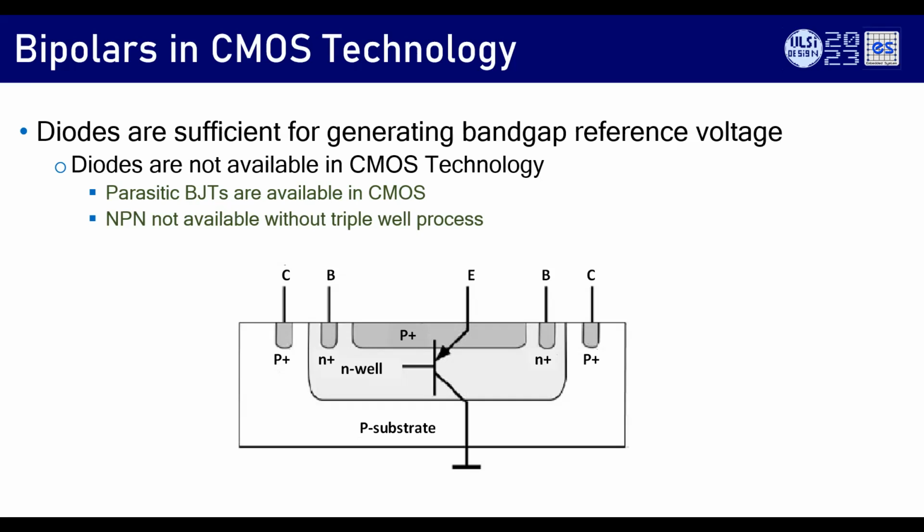So just an N plus inside P sub. Okay, you have N plus, you have P sub. You'll have some other transistors there, right? Yeah. Then you'll have a parasitic with that. So you can't have a diode, basically. That's a problem.